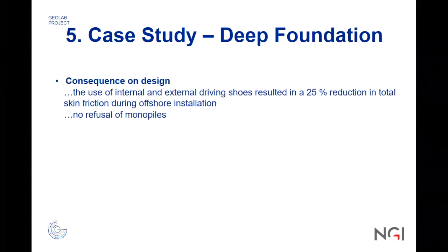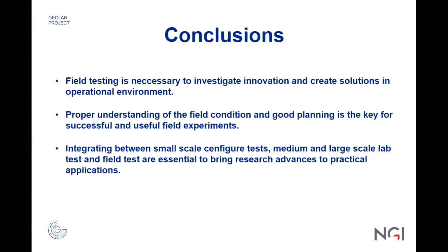The conclusion from the study is that the use of internal and external driving shoes resulted in a 25% reduction in total skin friction during offshore installation, and no refusal of the monopile when they actually installed the pile in reality in the project.